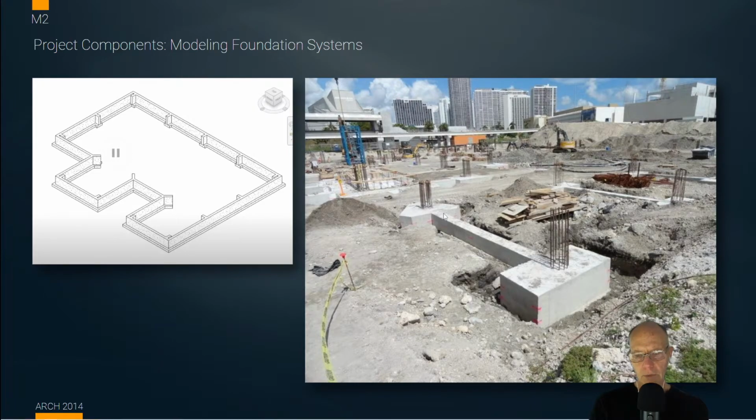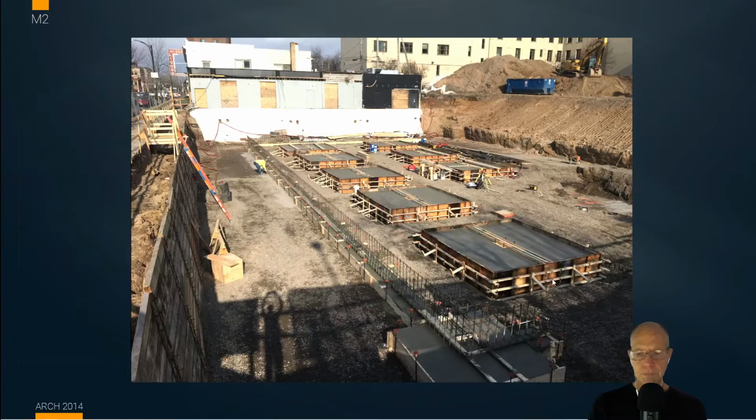They're a spreading of a pad of concrete, to bear the weight of what will be placed upon them over a larger area of soil. In this case, these pads have rebar sticking out of them, reinforcing steel, and a concrete column will be poured above this, and that column's weight will bear on this footer.